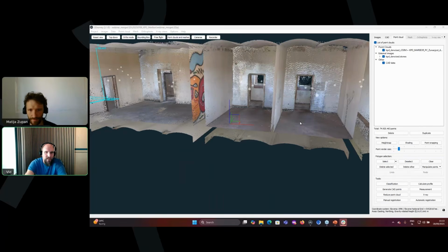One thing we did notice when doing the tests around our building is that if you go close to the building, you can experience a bit of multipath effect. So just make sure that you have good GPS and don't walk too much with the SLAM scanner very close to the wall. You can also scan it from maybe 5 meters away. You will still get very good results on the walls.